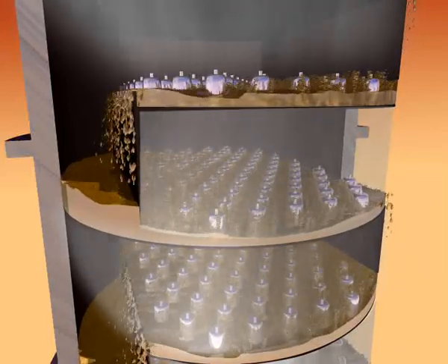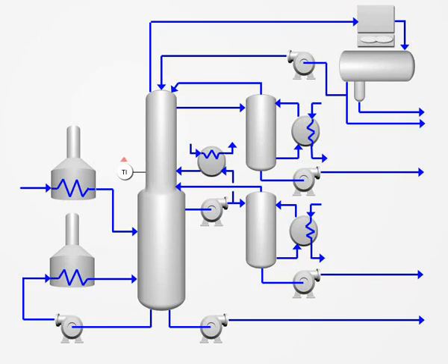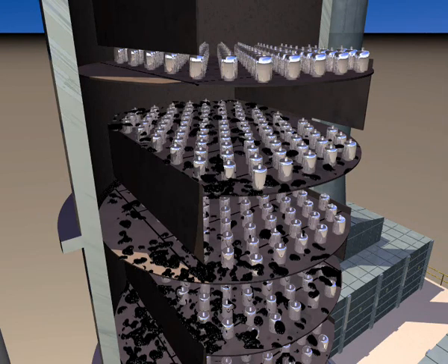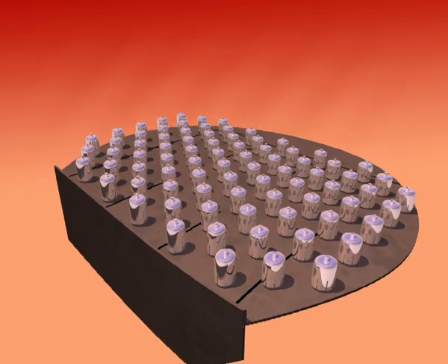In the situation where the liquid level is very low, the temperature will rise because the liquid-vapor rate is out of balance. Overheating of the oil can result in coking, leaving behind a solid residue that could plug the trays. If the liquid level is completely lost and the tray is running dry, the temperature of the internals itself will increase. The liquid acts as a heat sink to the heat the vapor is providing, and when lost, the trays can warp and bend out of shape because of the excessive heat.